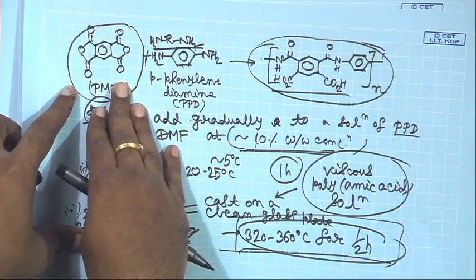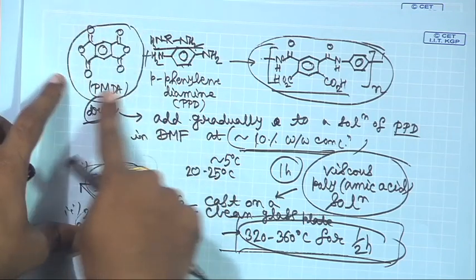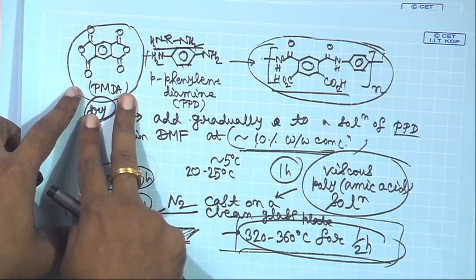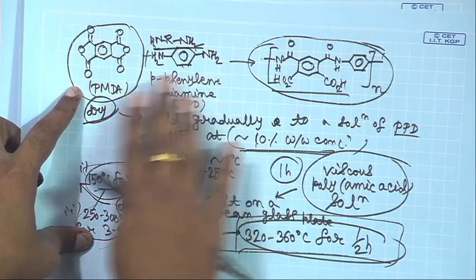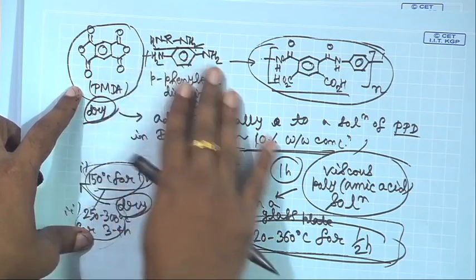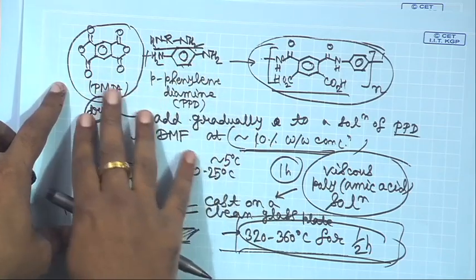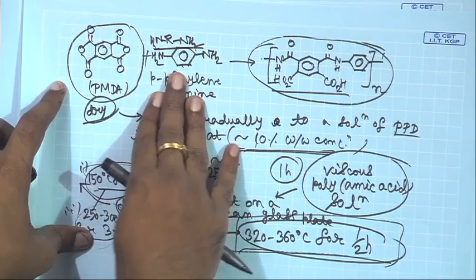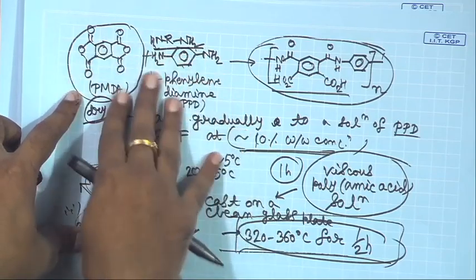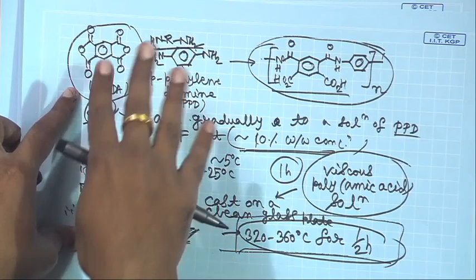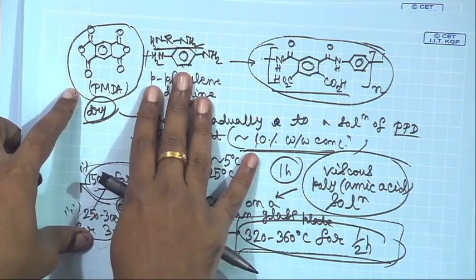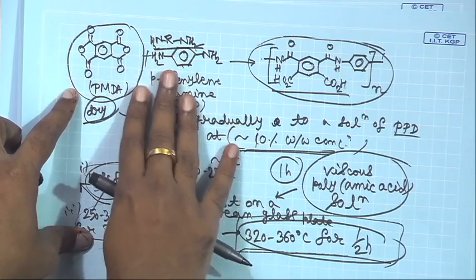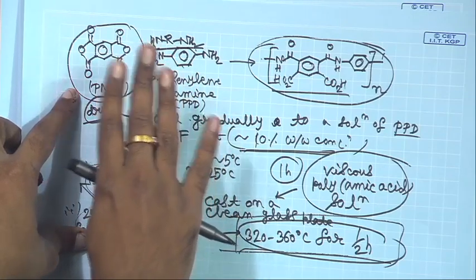So, if the rate of dissolution becomes lower than the rate of polymerization, then the process will become diffusion controlled, and in effect it will become a solid liquid interfacial polymerization reaction, because it is a solid, it has not dissolved yet, but it has started to react, because this reaction is faster than the dissolution process. And you know, for interfacial polymerizations very high molecular weight product will be formed almost immediately. We have talked about this before,